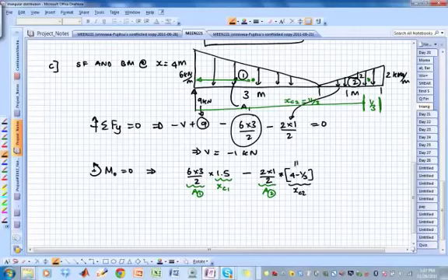That turns out to be equal to 11/3. That's this one. Remember, it's the coordinate of the second one, not just the location. You can't just put 1/3. You have to measure from where you're doing the origin. That's why it's important for you to make sure you know where you're taking moments around. I'm taking moments around this point, so I need the distance, the distance from here all the way to there. So please remember that.